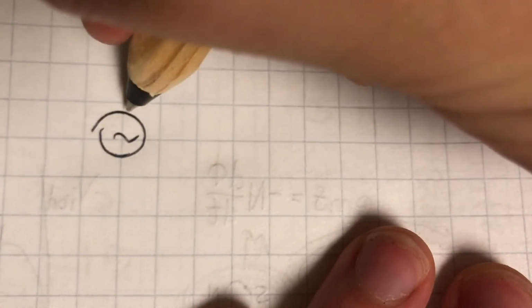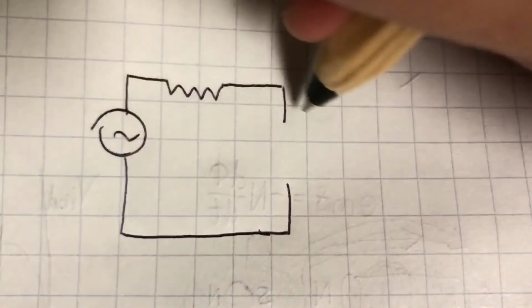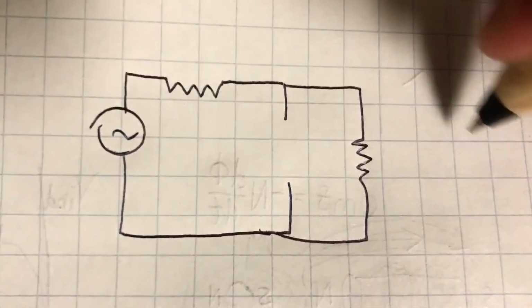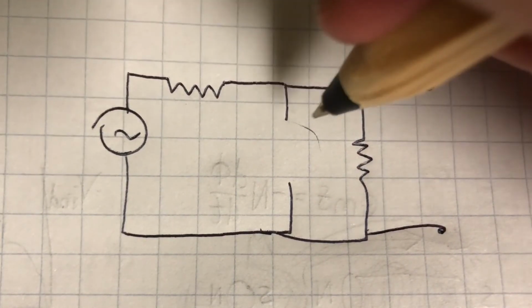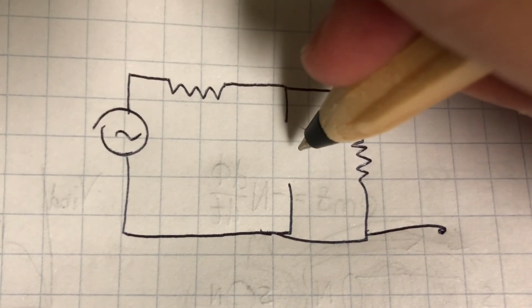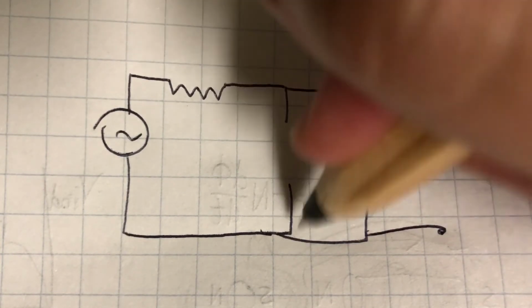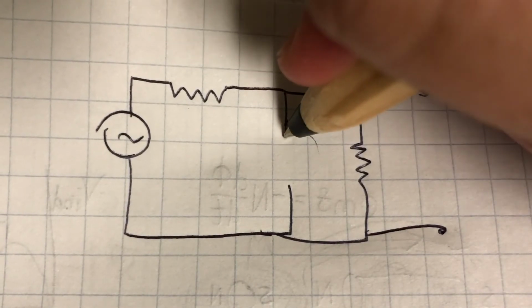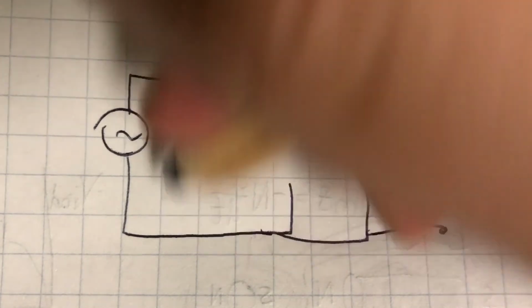So again, we're going to have AC current, that, and this is our volume, and then output. Okay, so you see that I left it blank here, okay? And this is because at this stage in time, the capacitor is full, right? It's fully charged. And we know that when a capacitor is fully charged, there's not going to be any current coming through here anymore, right? It doesn't need anything. There aren't going to be any more movements of electrons through this, right? So the current's going to be very low for the overall circuit.